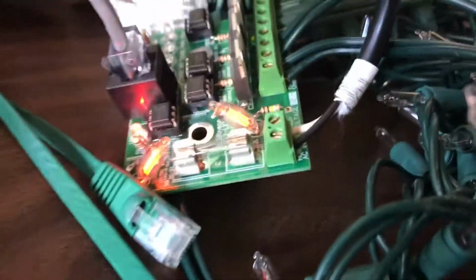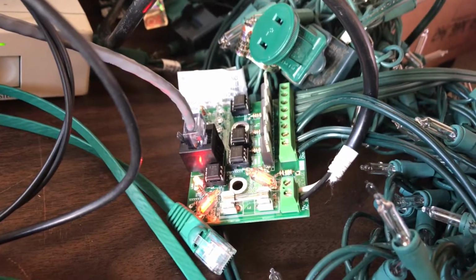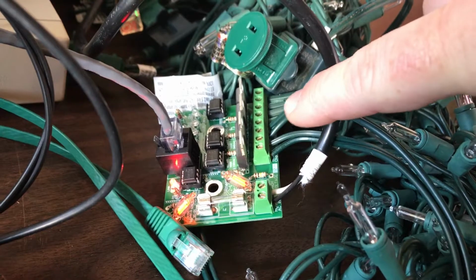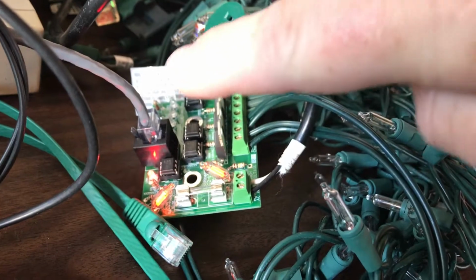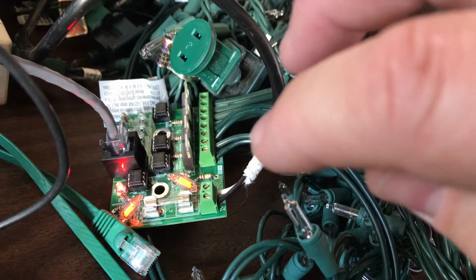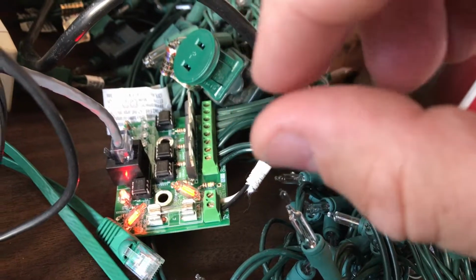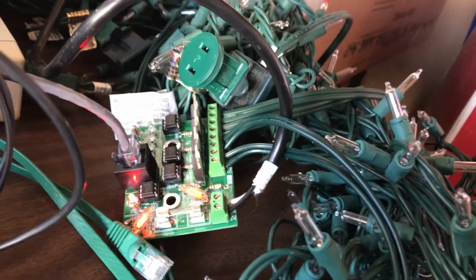And by relay board, I'm talking about something like this guy here. My little shrink wrap label getting in the way. So this one is the SSR Neon G2 LED. So your light outputs right there. Input for AC right there. And then the Ethernet cable that's used for serial communication. There's four cables in there for controlling the solid state relays, and then 5-volt and ground.